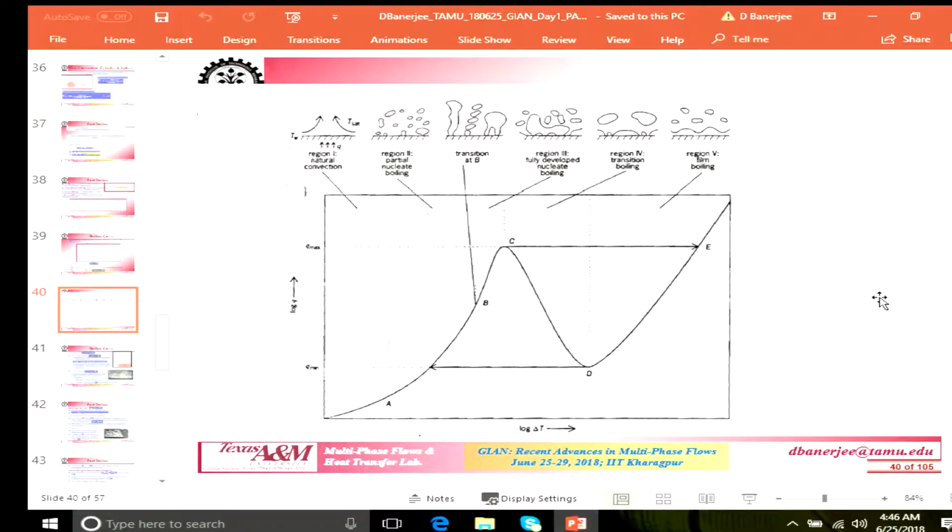So when you measure roughness, there is a roughness parameter that measures the standard deviation of this profile, right. But in any case, let us assume that you have a plane surface, fairly non rough, fairly smooth. Let us say I have a silicon wafer which is atomically smooth, right. Your typical silicon wafers are single crystals, and they are polished to almost single lattice constant surface roughness. It is almost flat and plain. So on a surface like that, if I am operating pretty high up here, do you think that vapor blanket is stable?